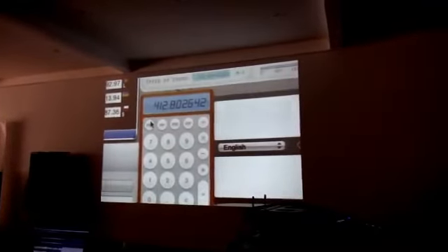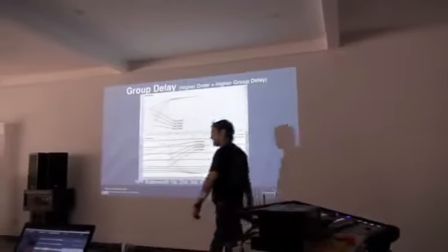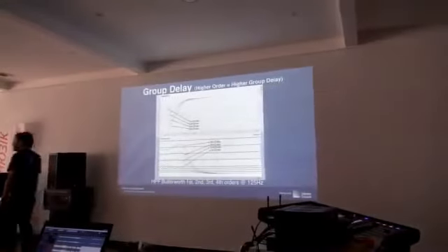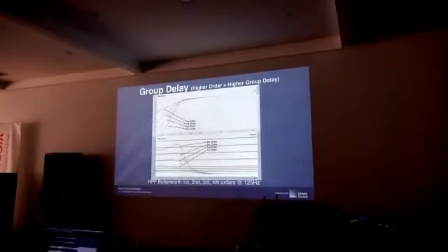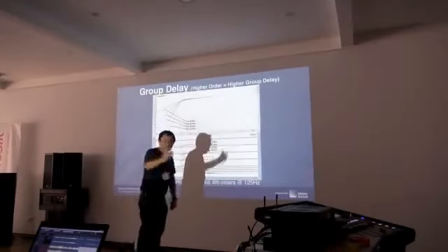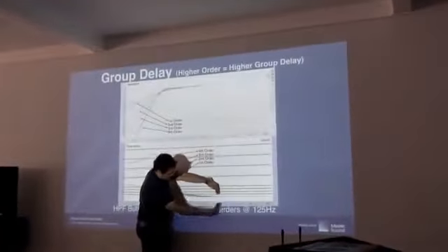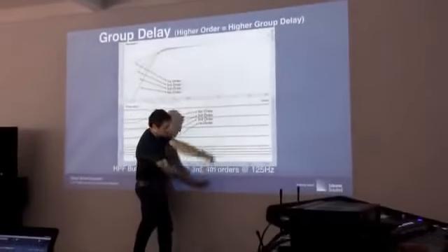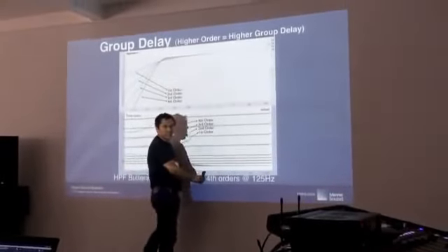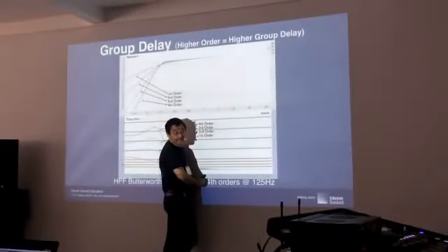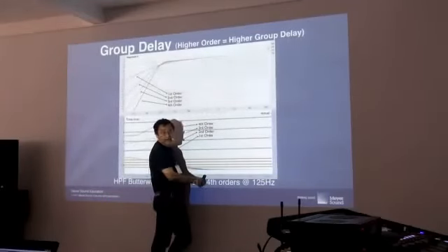In the processor Xilica the parameter of taps is in steps of 50. That is around 0.5 milliseconds. So if I select 50 taps, 0.5 milliseconds, and I start to move my high pass, high pass order number 4 will stop at 1 kHz. And it's not possible to go lower if I am using FIR filter. If I want to go lower, I need to add more latency.